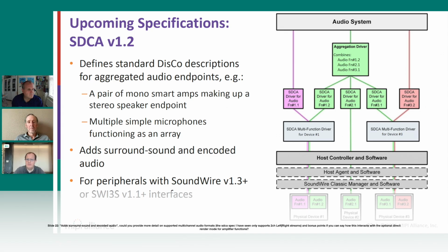And that SDCA feature is designed to be used in concert with some sort of spatialization engine running on the host, and that might be as simple as an AC3 decoder, or it might be a stereo image expander or some kind of fancy directional audio thing. So it's different but related. And Render Direct, as I think you've observed, is already defined in SDCA 1.0 and 1.1.